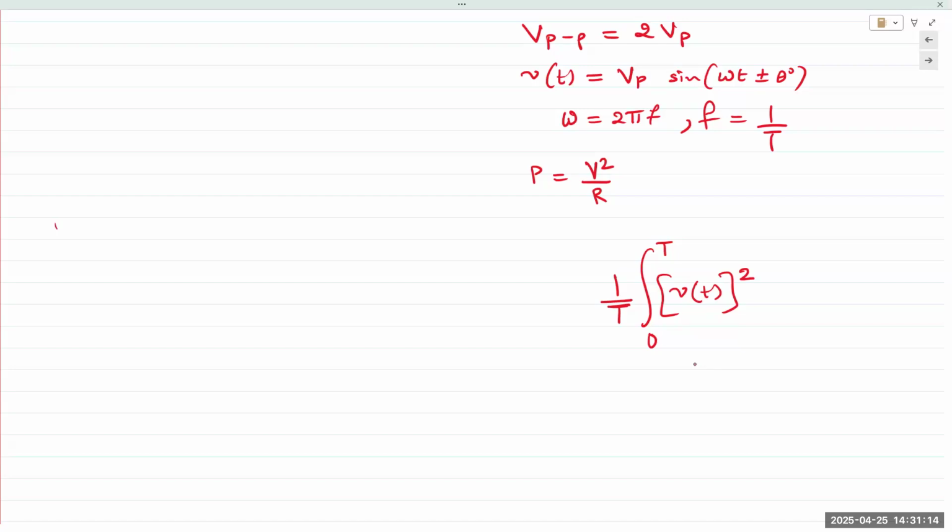And then because we took the square first and then we took the average, now we take the square root of that answer. So the RMS value of the waveform is literally the square root of the mean of the square of the waveform, hence RMS, root mean square.